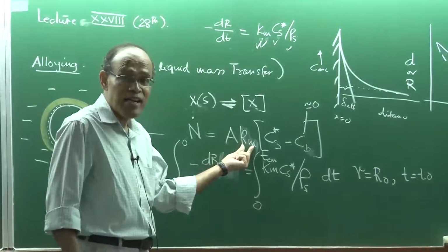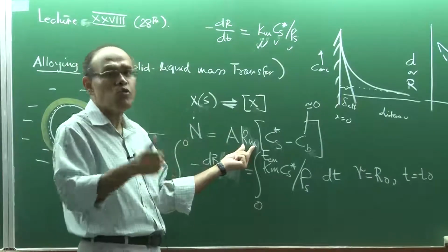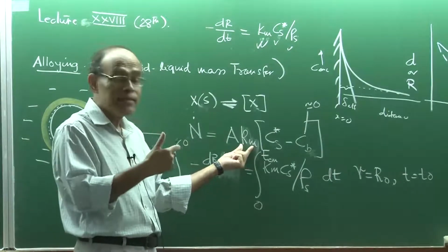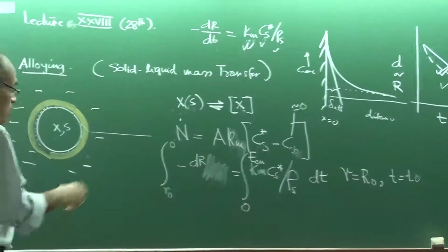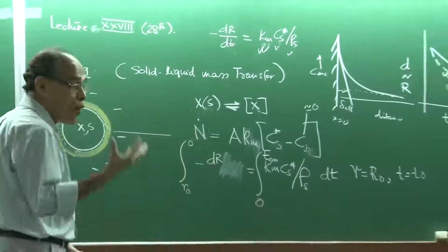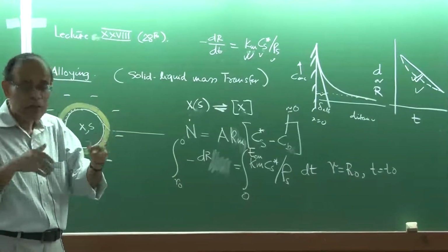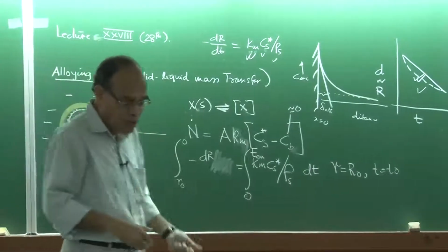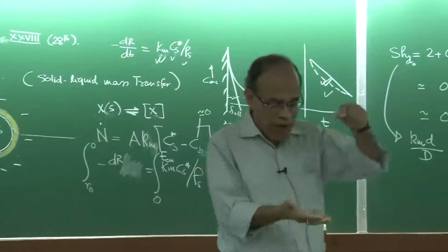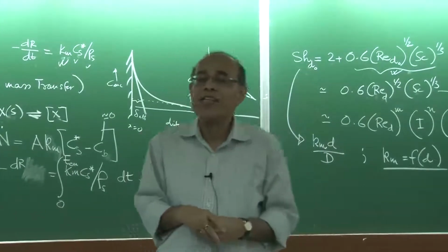This embodies the stirring, the intensity of stirring, what stirring you should be applying. And then what should be the concentration, the complete melting time, what should be the size, because if you add a bigger size, it will take a longer time to dissolve, and you have a finite processing time. For example, when you make alloy steel,